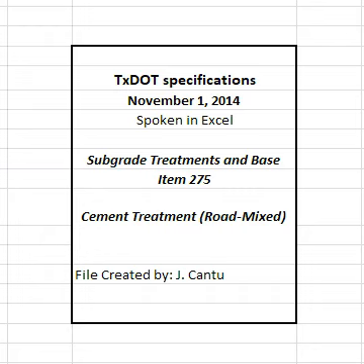5. Measurement. 5.1 Cement. Cement will be measured by the ton, dry weight. When cement is furnished in trucks, the weight of cement will be determined on certified scales, or the contractor must provide a set of standard platform truck scales at a location approved by the engineer. Scales must conform to the requirements of Item 520, Weighing and Measuring Equipment. When cement is furnished in bags, indicate the manufacturer's certified weight.